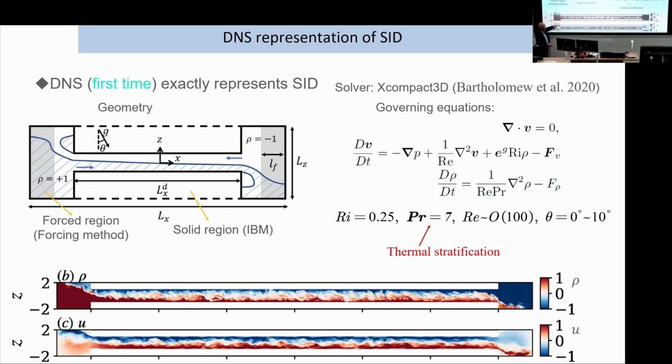So these are no-slip boundaries with no fluxes, and we then have reservoirs where we artificially reduce the velocities to zero and restore the density to the original value. And we do that in the momentum and mass equations by these two forcing terms that are in red, which essentially slow the flow down here, restore the density, and allow it to carry on as before.